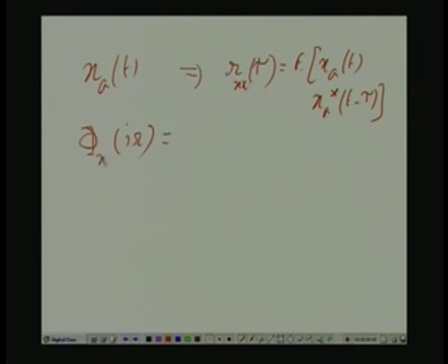So, similarly, here Φxx(jω), which we know is the Fourier transform of the autocorrelation function R xx(τ), that is, the integral of R xx(τ) e to the power minus jωτ dτ from minus infinity to infinity. We have seen that even though the random process is complex valued and therefore the correlation is a complex valued function, the power spectral density is a real valued function. Okay.